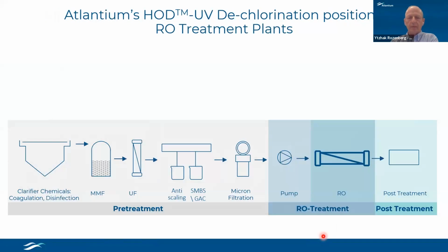Where to implement the UV in the facility? This is just an example, starting with a clarifier, multimedia filter, ultrafiltration, anti-scaling, SBS or active carbon, microfiltration, pump, RO, and post-treatment. Where shall we use the UV?